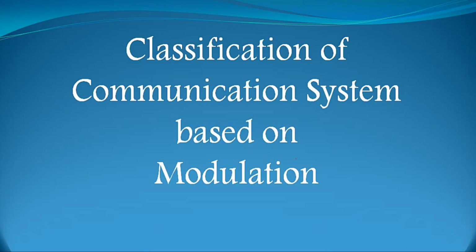So we know that modulation is a process of shifting a low frequency signal to a high frequency signal. Here, for modulation we need a high frequency signal. From the information source we generate a baseband signal, or we can say an information signal or a message signal. That low frequency message signal or baseband signal is superimposed with a high frequency carrier signal in order to get a high frequency modulated signal. In simple words, modulation is the shifting of a low frequency signal to a high frequency signal without changing any information. Based on the high frequency carrier signal, the modulation process will be done.